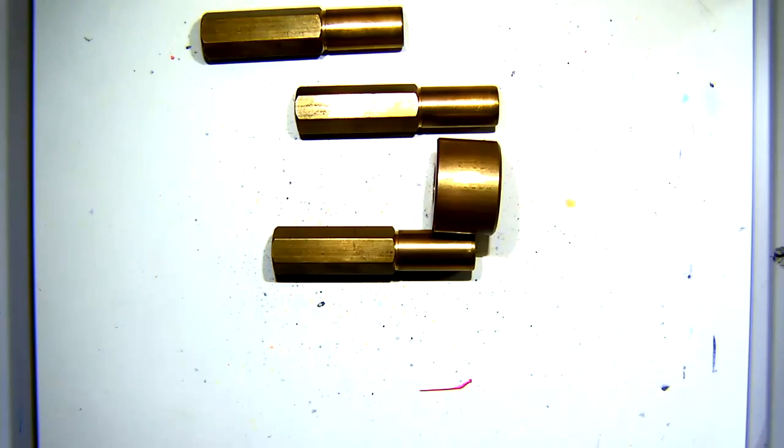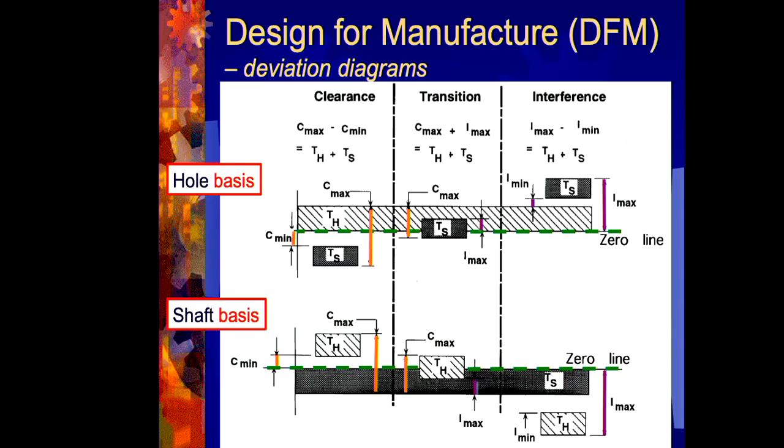Hole base. What that's saying is that one of the dimensions of the hole is at a 0 point, just to make life easy. Everything's not some fancy, micron-based number. We can go the other way, and instead of what I was just showing, I could have had 3 holes and 1 shaft: one clearance hole, one transition hole, one interference hole, and they're the three tolerances associated with that, with one shaft sizing with a base dimension associated with the exact value we're looking for.